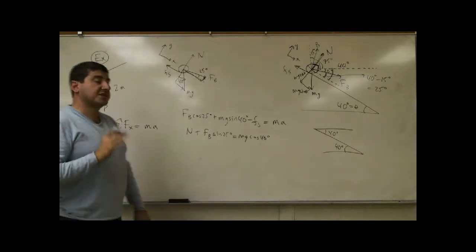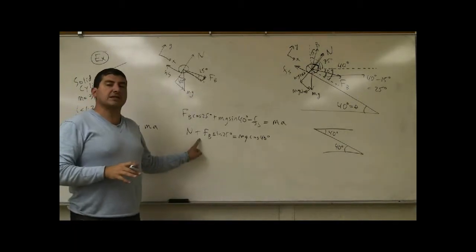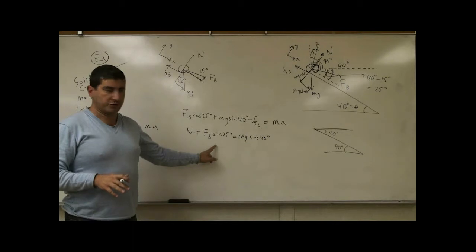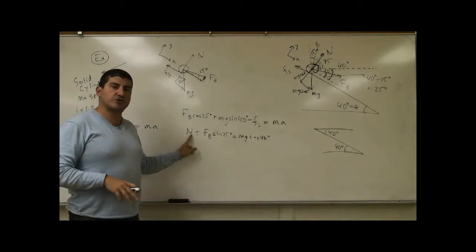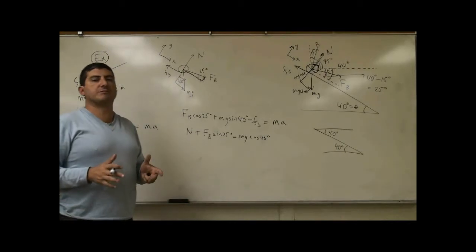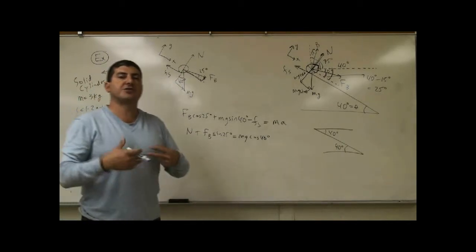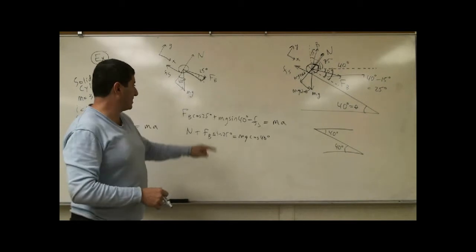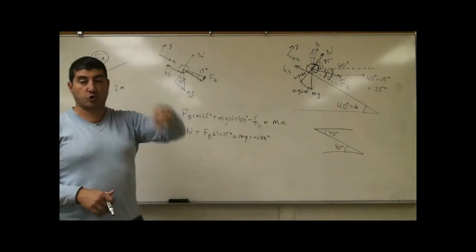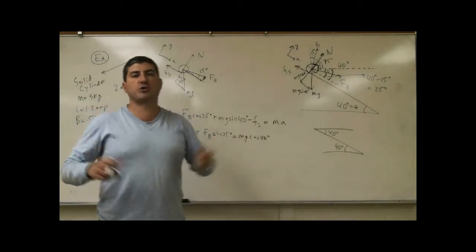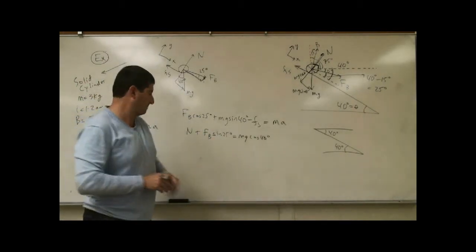It's going to turn out that we're really not going to need the vertical force, because the vertical force is mainly so that we can solve for the normal force, but this problem will not depend on our knowledge of the normal force, because in order to find the friction force, Fs, we'll just analyze the torques on the system, and the torques will already take care of everything.